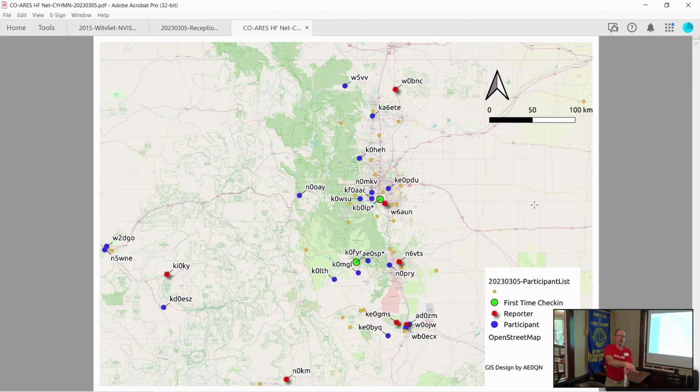You don't need a tuner once you trim the legs to the right length. When you're on one band, the other band at that frequency will be an extremely high impedance, so your RF doesn't even try to go that way. It goes into the correct legs, so you don't need a switch at the top or 2 coaxes or a tuner or anything.